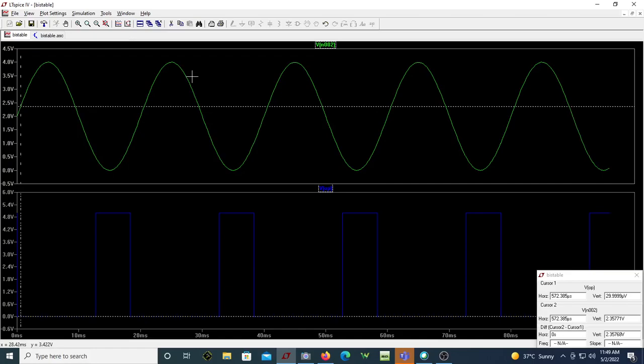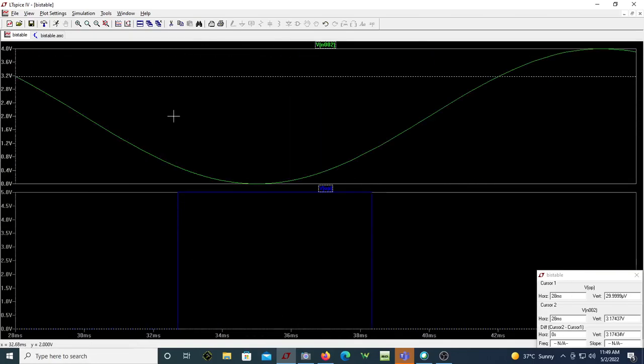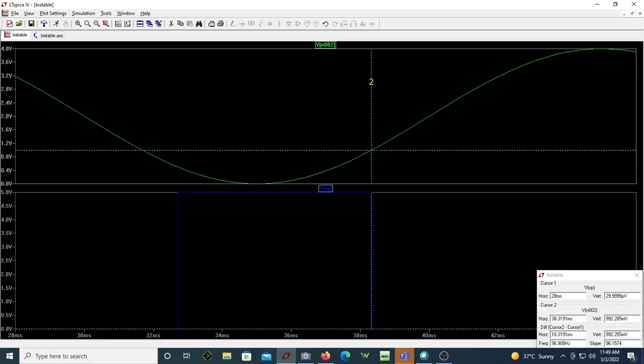Okay, let us trace it and try to find out what happens here. Can you see input voltage is going down here whenever it tries to go below 0.5? Can you see this is 0.5 somewhere. When it is going less than 0.5, it goes to high state. It stays in high state as long as the input is lesser than VTH. VTH is 1 volt. So you can actually move this and see here.